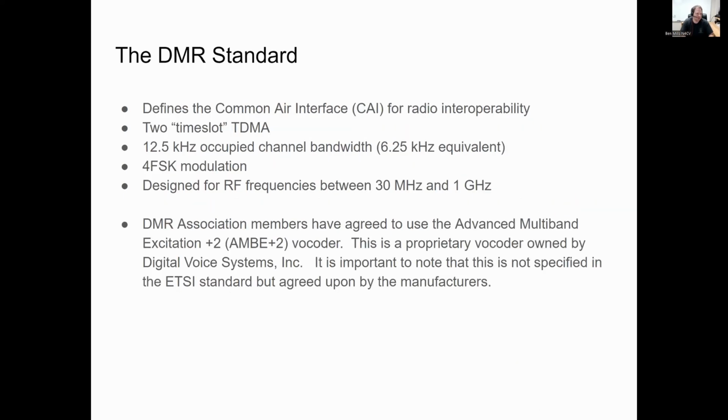So a couple of things are different about DMR. The biggest is that it actually is a time-slotted mode. Our voice is processed through digital signal processing and broken up to take about half of the amount of time to transmit our voice packet than it would if I were speaking purely into an FM microphone and up converting. So we're time slotting for TDMA, which will be important here in a minute.